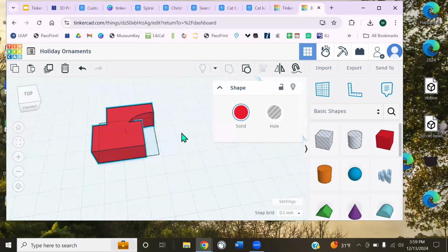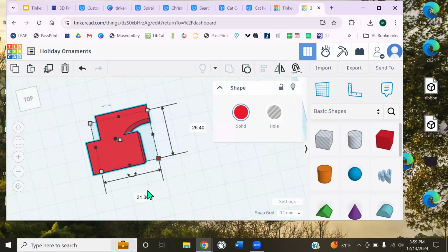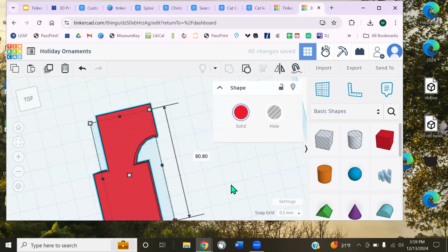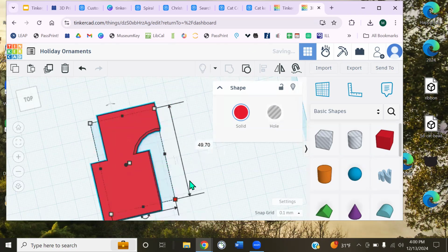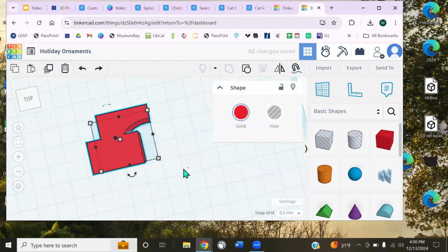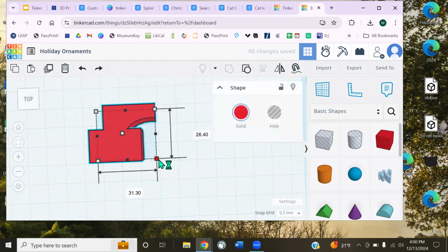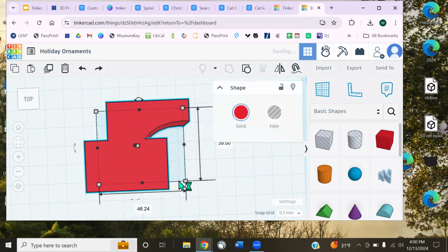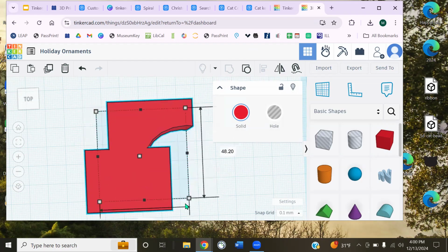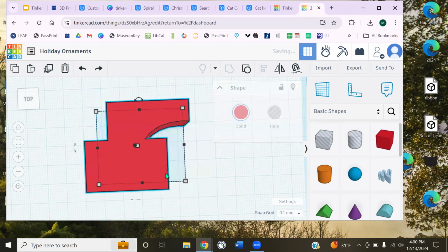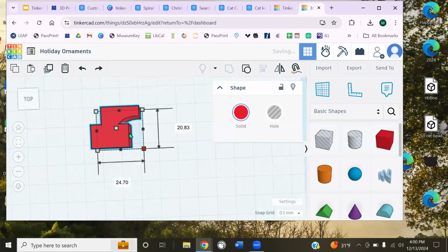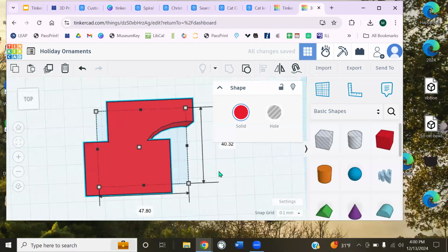One thing that we'll notice is that as we use this diagonal one, it's skewing the object. I might want to pull it out like this, but if I'm a little bit sloppy, it's skewing it both along the X and Y axis. So what we can do is hold down the Shift key while we do this, and it's automatically going to keep the X and Y the same. It's not going to let me skew one without skewing the second, so it's going to pull it up not like this, but like this, nice and smoothly, keeping the same basic shape, just scaling it up and down. That's my Shift key.